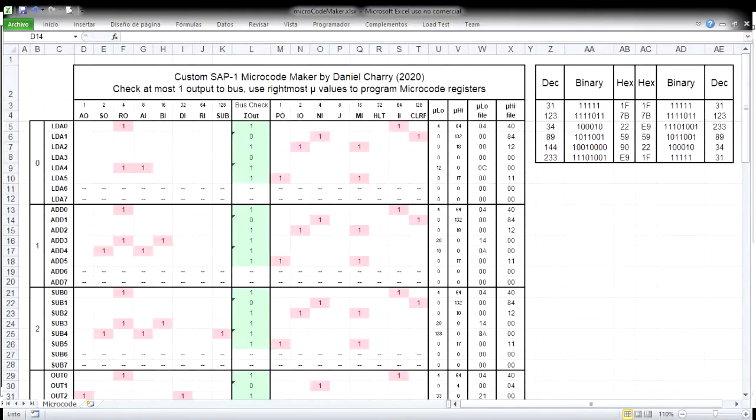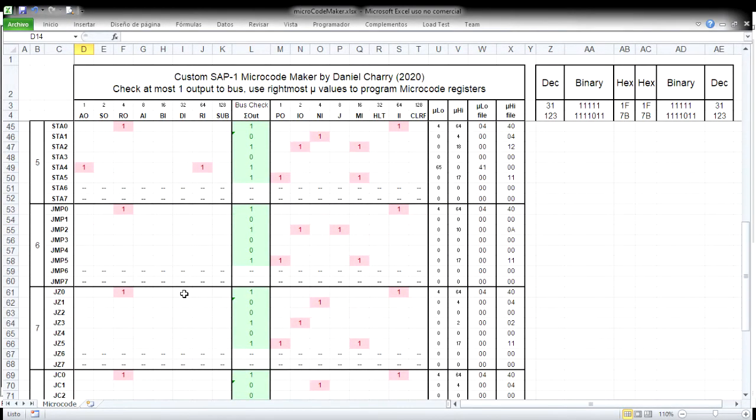So let's try to understand it more by an example. Let's take a look at the jump instruction. You can see that the jump instruction is quite clear. It doesn't require many microcode steps. What we do is simply make a fetch cycle, which is getting what's on the RAM and putting it in the instruction register. And then we make the following.